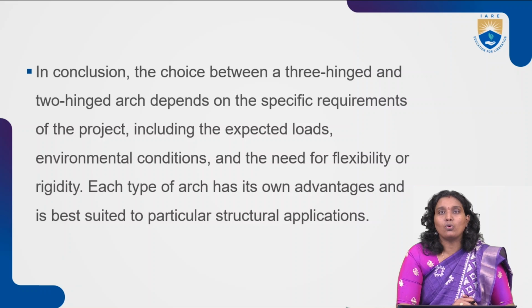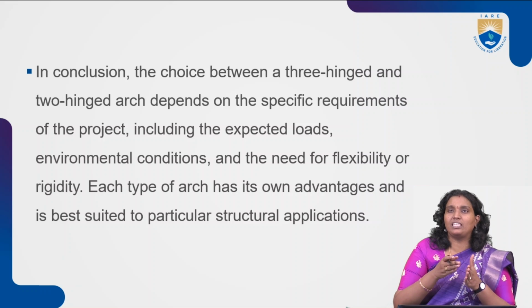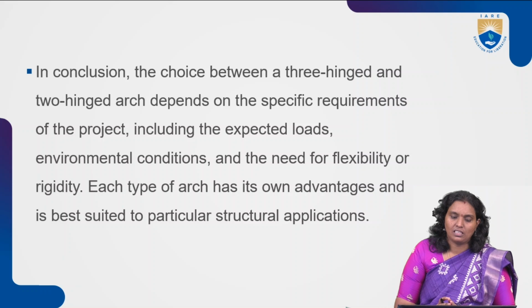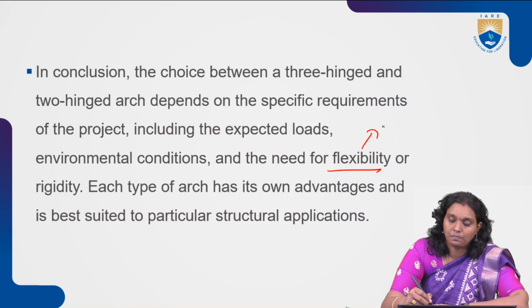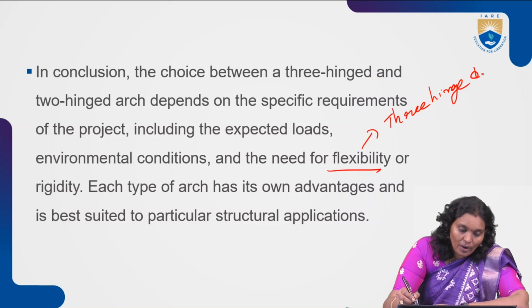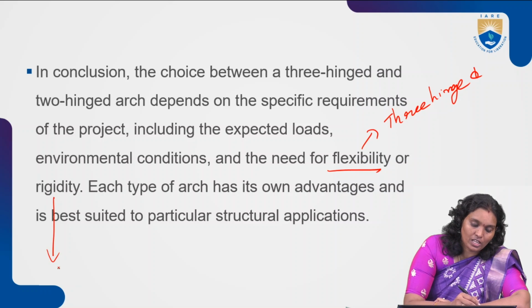In overall conclusion, the choice between three-hinged and two-hinged arches depends upon the specific requirements of the project, including the expected load, environmental conditions, and the need for flexibility or rigidity. Whenever we need flexibility, we choose three-hinged arches. If we require rigidity, we choose two-hinged arches.